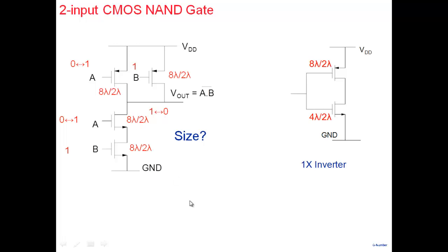All right. Now, once you design this gate in this particular manner, let's evaluate this particular gate. We designed this particular gate keeping in mind the delay. We are sort of balancing the drive strength. So let's go back and see for this design what happens to the VTC. Noise margins are important, voltage transfer characteristics are important. So let's look at the VTC under this design now.